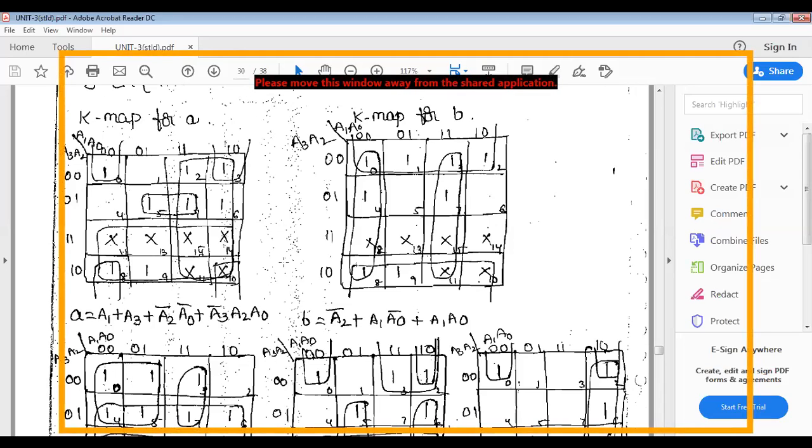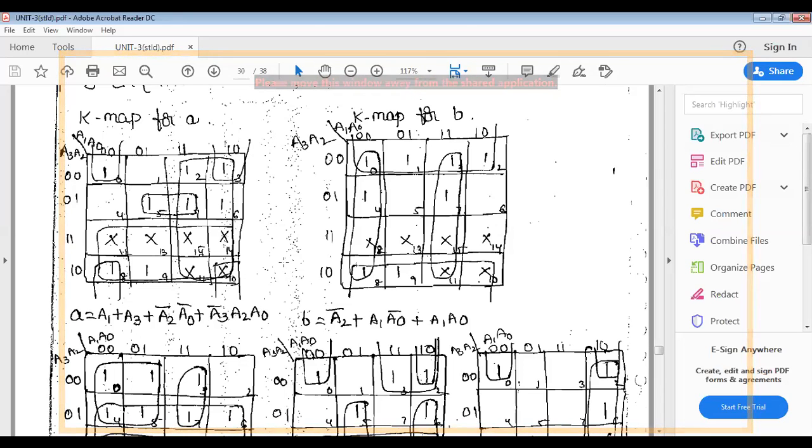Don't go for 5 and 7 only, the 2 box. You can use 5, 7, 13 and 15 as a 4 box combination. To cover the 5 minterm, you can use the already covered 7 and the don't cares 13 and 15.